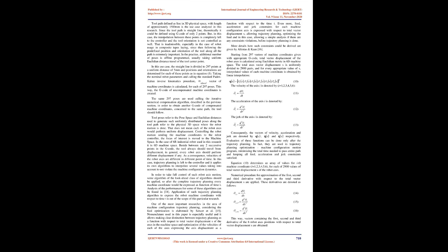The forward kinematics algorithm with calibrated values of the parameters is called in the next step, and its output is used to determine deviation from the desired pose. Such deviations are calculated and transformed into the pose space in order to obtain 6 scalar components of the deviations vector. The vector fx_i determines the contribution of the i-th machine coordinate in pose coordinates changes.